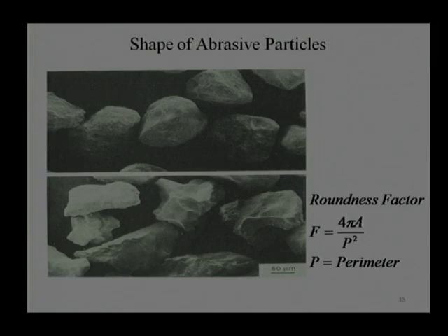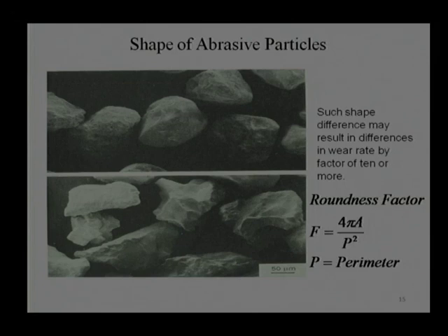in 3 body abrasion compared to an irregular shape, and that is the reason many times we use particles for lubrication, and the particle shape is kept spherical, which is not going to cause any failure, which is not going to cause abrasion of the surface. That will always be advisable. Choose the particle shape in such a manner that it causes lesser abrasion.